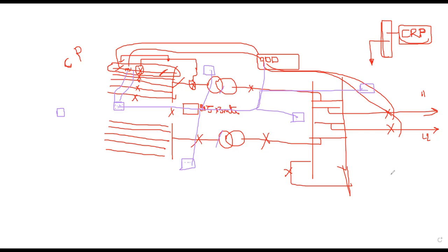Suppose in the olden days, the interlocks we mentioned, like the isolators to be opened, were mechanical interlocks. They were all hard wired, and if all the conditions were satisfied, it would give a signal, an output. This hard wiring was inside the control and relay panel, so the panel size was larger in the olden days.